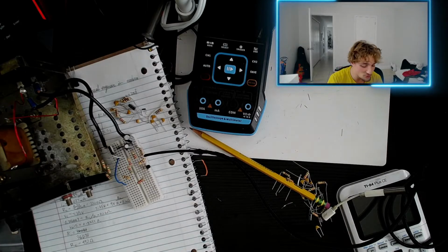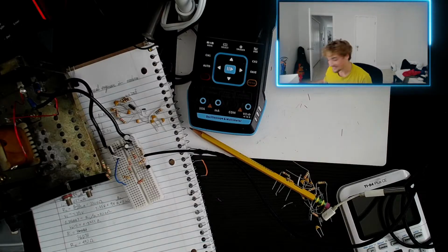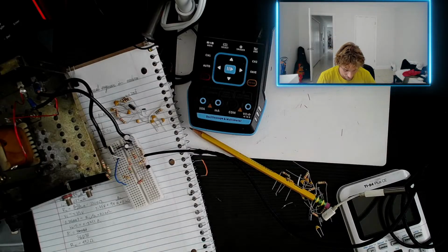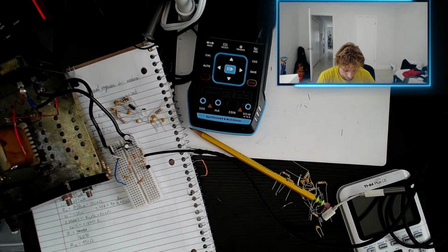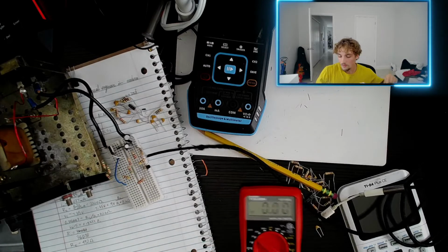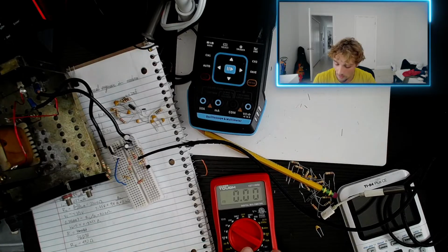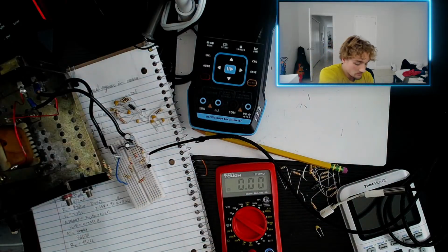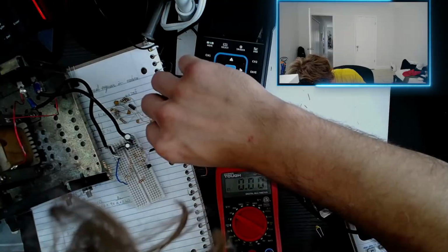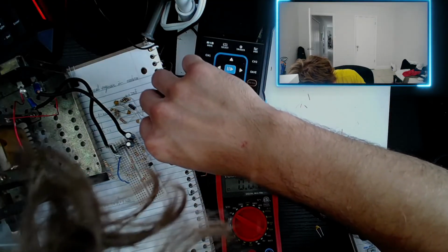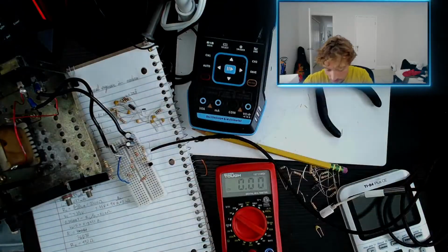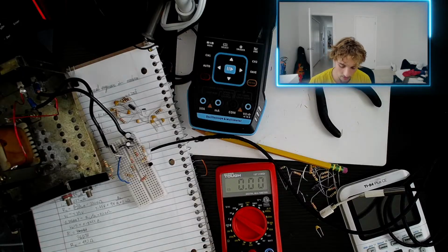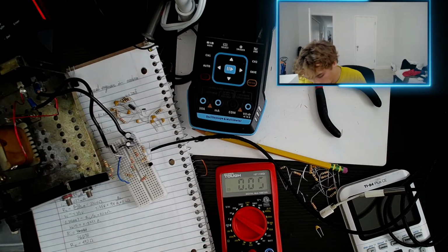Alright, now let's do some measurements. Okay, so we're gonna pull out the multimeter here. And now, referring back to our theorized values, let's go ahead and measure around the circuit. So I'm gonna set to 20 volts on DC. Oh my gosh, those aren't good anymore. Those have kind of broken off pretty bad. Okay, so what did we want? We wanted like 7 point something volts across our RC. So let's go ahead and measure that.